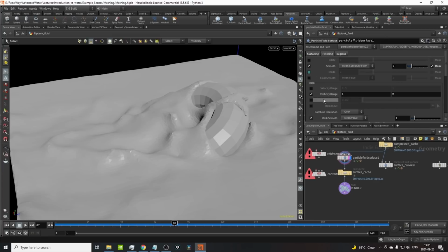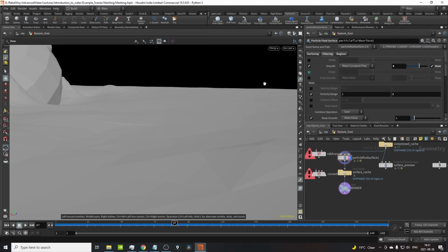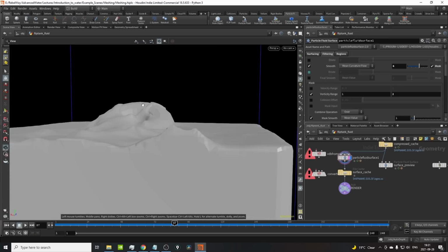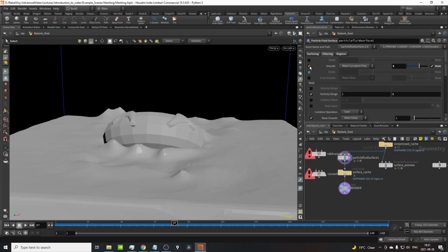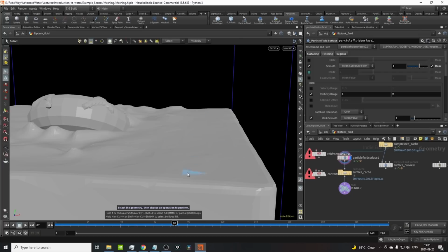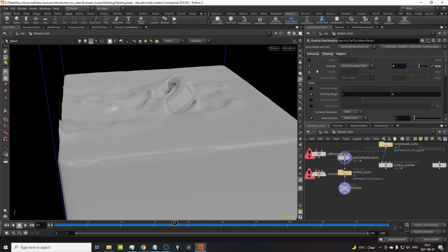Turn this off and we go back up here to our smoothing. I can set this to a 4, maybe even a 6, right? If I want to be really crazy. I get this really smooth surface here. But as soon as we're in our simulation area where stuff is happening, we're still retaining all of this detail. So there's really barely any change in our simulation besides just smoothing out these areas out here. So that's smoothing. Very useful. Always use it. Really neat little feature to have.